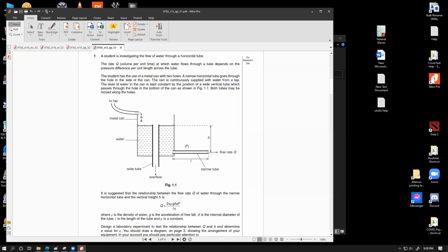So you would have the time measurement in your stopwatch, and you have collected certain amount of water in your bucket. I'm talking about bucket because maintaining a measuring cylinder immediately at the bottom of the flow rate channel narrow tube might not be a good idea. So you collect the whole water in a bucket, and then you take your time to measure that amount of volume of that water using beakers or measuring cylinder, however appropriate.